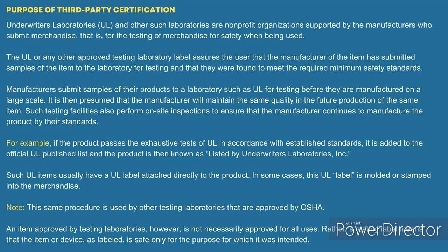It's just like if I had a hardwired unit, and they provided it on the secondary side of that unit. It's where the human interaction comes in. When you look at receptacles that are outside, why do you have GFCI protection for all of those receptacles? Because you have human interaction plugging in out in a damp or wet location.